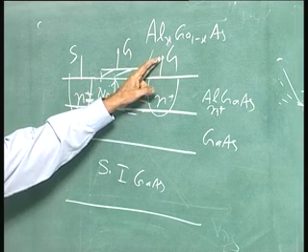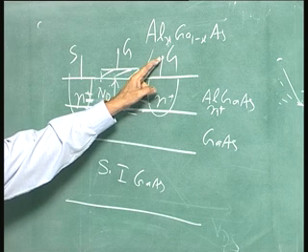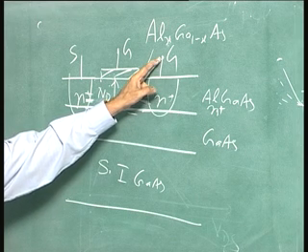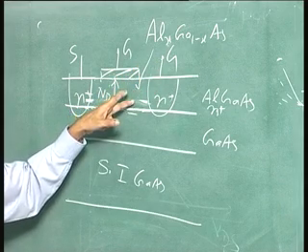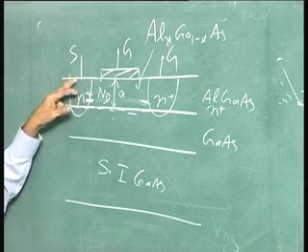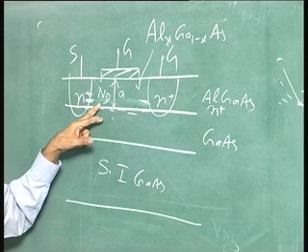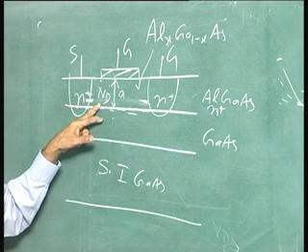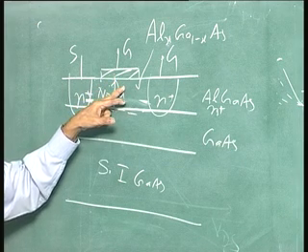X, there is an upper limit of about 0.3 or so. People do not go beyond 0.3 because of the traps which are introduced, and because of difficulty in making ohmic contact onto that layer. Okay. Now, doping has an upper limit, because the Schottky will start conducting.